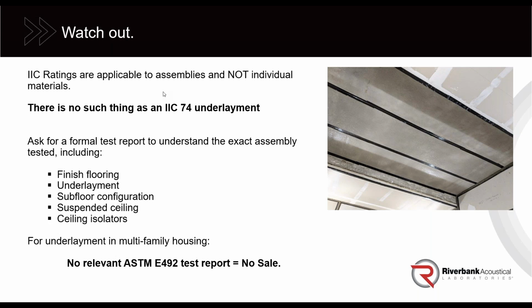As we mentioned before, and this is really critical to hammer in on IIC performance: IIC is not a materials rating. IIC is not a rating on an underlayment or a floor covering. IIC is a rating on the entire subfloor, of which that floor covering or underlayment is one component.